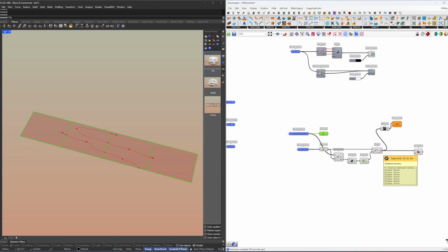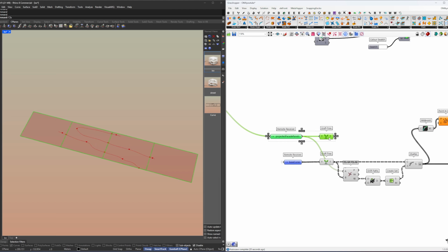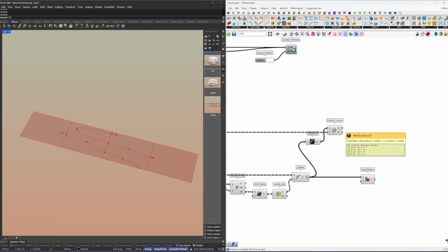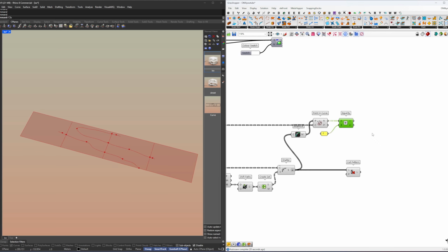Now, since this is a flattened list, I'm going to graft the facade panels for every elevation panel 1. And it also says it gets a value of 2 as soon as it's inside a curve. Right? So we're going to check all these values and we're going to check whether they are equal to 2. And if that is the case, it gets a true. Otherwise, it's a false.